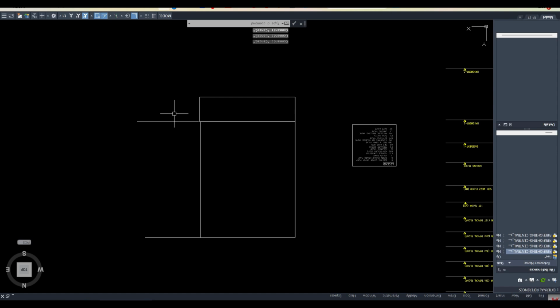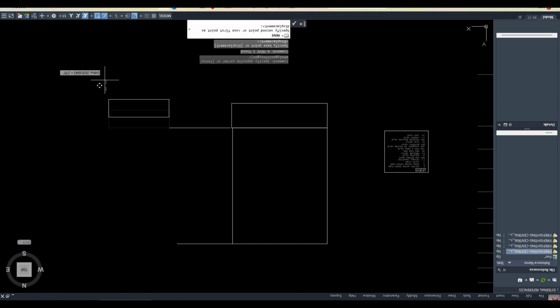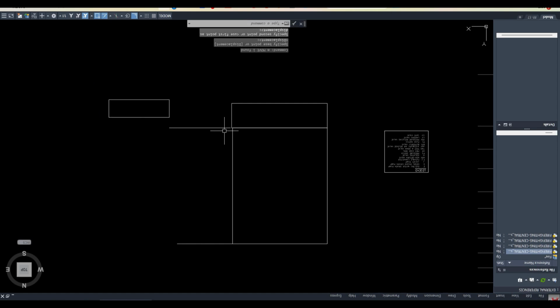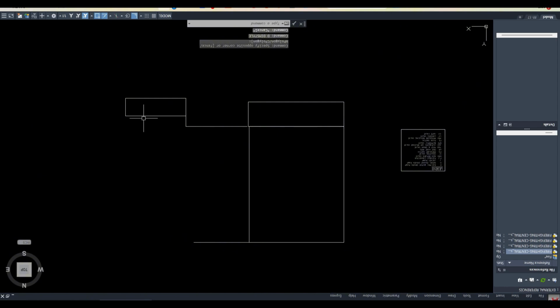So from where do you have to measure? Maybe after the ground floor there is a grade level. Grade level means the road levels. You are making roads and all, and roads are obviously not at the same height as the building, right? So it's something like this. Your car is running here; maybe there is a basement, but you forget about that, the basement will not count. So the distance will not be from the ground floor to the roof, but from the grade level to the roof floor.